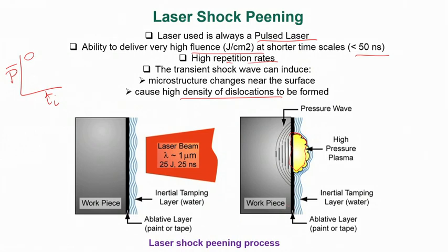The beauty of laser assisted shock peening, please remember we are talking about shock peening and not shot peening, is that it affects a very thin layer, typically a few tens of micrometers or even less. There is no dimensional change, no compositional change, no distortion, yet the surface develops a fairly high residual compressive stress of a few hundred megapascals.